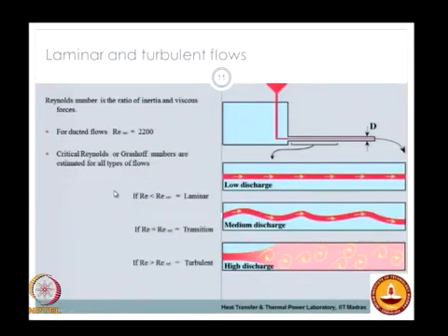Now the other important classification is based on forced convection, where the characteristic dimensionless number is the Reynolds number. For internal flows, such as flow through ducts or channels, the critical Reynolds number is around 2200, and if the Reynolds number is less than the critical value, you typically find a very orderly behavior of flow in a streamlined pattern.